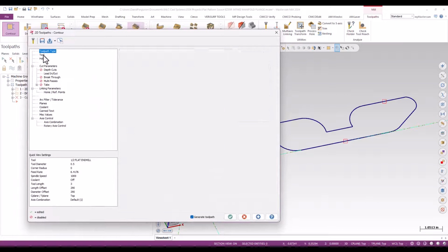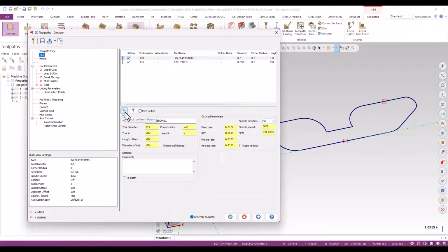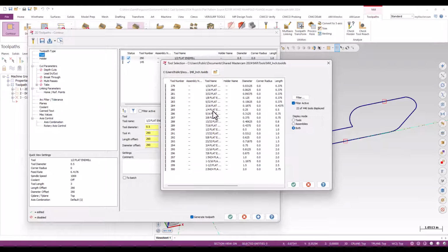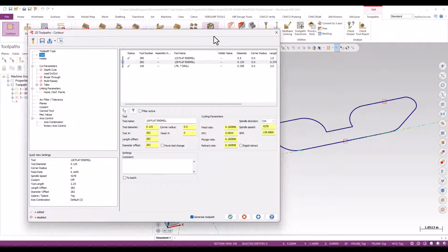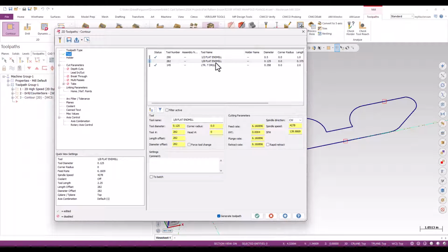We're going to go to a slightly smaller tool. I think that 1/2" end mill might be a little large for that. So we're going to go down to an 1/8 inch, again just so we can get in there a little bit more. Your experience may vary. We'll see how it goes. Again, we're just trying to show you how to set up a basic tab run for a contour. So we'll just use that tool for fun.